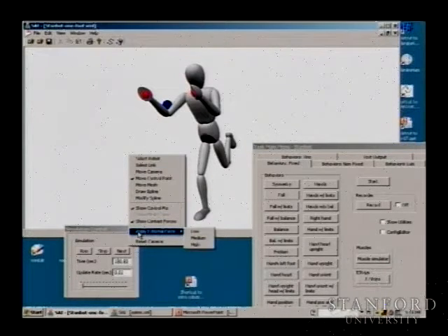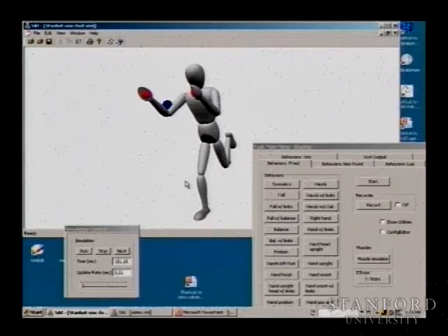You can not only interact with it by moving the goal, but you can go and pull the hair. Ouch! You can pull anywhere. When I click here, I'm computing the forward kinematics and the Jacobian, and I'm applying a force that is immediately going to produce that force computed by the Jacobian on the motors, and everything will react in that way.